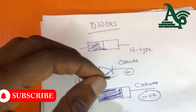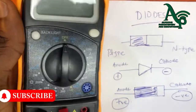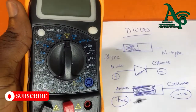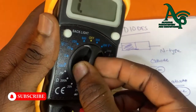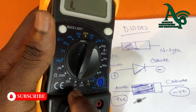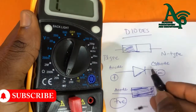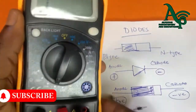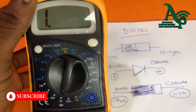of the diode. Let us quickly look at how we can use our multimeter or digital multimeter to test our diode. Now you have to turn the knob of your multimeter to where you have the diode symbol. This is the diode symbol here, which is exactly what we've discussed earlier. Now let's see how we test a diode using the multimeter.